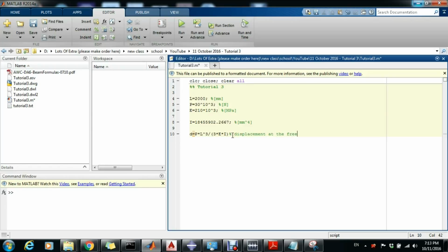at the free end. But we also want to compute a maximum normal stress, as we said in the beginning. So we know that the normal stress, we call it sigma xx, equals M, the bending moment, divided by I, moment of inertia, multiplied by y in general. So this is the Navier formula. And if you want the maximum stress, y is h over 2. It doesn't matter if it's compression or tension. This is a cross-section symmetric on two axes. So on the top fiber, this will be the maximum tensile stress, and on the bottom fiber, this will be the maximum compressive stress.